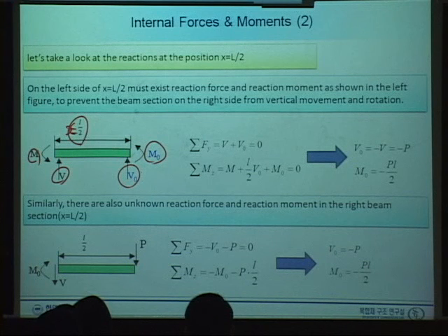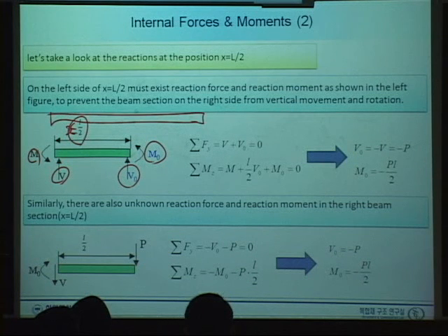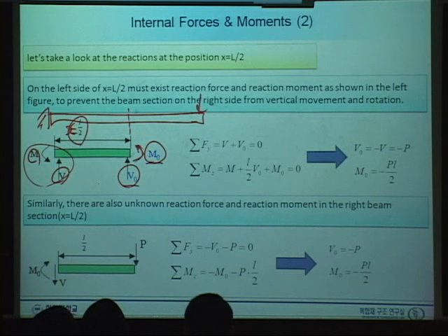The key point is that this is from the whole beam, and the internal forces will be present here. So to calculate that, we have this one, which we already calculated using force equilibrium, and then we just have the unknown M here, and again we apply force equilibrium and moment equilibrium to this structure.